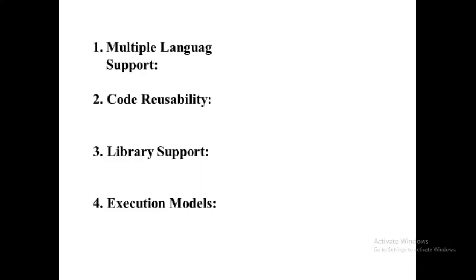Third, library support. The IEC 61131 standard includes a library of pre-programmed functions and function blocks. An IEC-compliant controller supports these as a firmware library, that is, the library pre-coded in executable form into a PROM or flash RAM on the device.